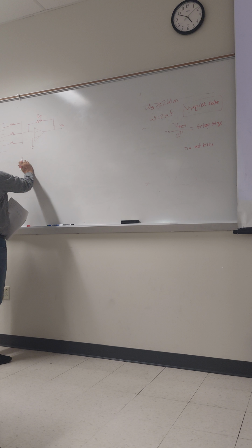Here, in a binary weighted digital to analog converter, resistor values are chosen according to the weight of each binary position to ensure the output voltage accurately represents the digital input. Because we have to represent accurately the bit pattern, the bit position will decide the weight. That's why we need to maintain the R value, choosing the resistor value in the binary weighted way.